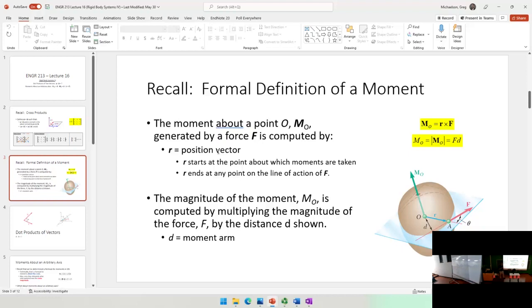Now, if you have long, slender elements, especially ones that have open cross sections, they behave the weakest when they're being twisted. A good example might be a transmission tower. If you've ever been driving on the interstate, you see those big towers, those big 3D trusses that support the power transmission lines, you know what I'm talking about? Imagine if one of those towers gets hit with some wind in some weird direction.